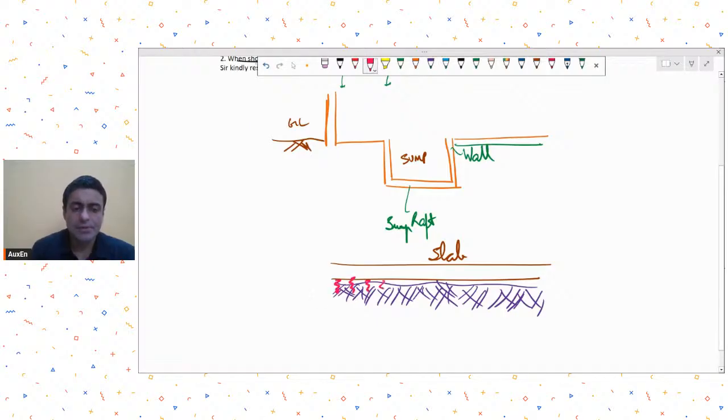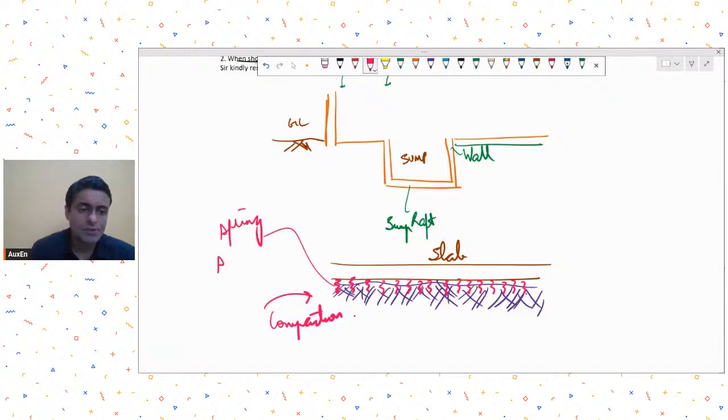Okay, so it's a spring support where the stiffness offered by this compacted soil fill will depend on the compaction of this earth surface. Now how to find out the spring stiffness of this soil? There are some documents that you could refer to. There is a document named TR34, I think, which is a document on industrial floors.